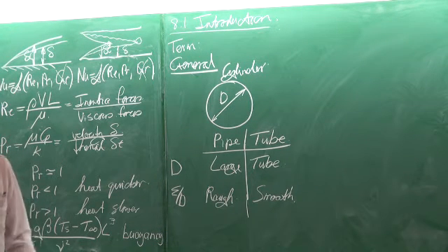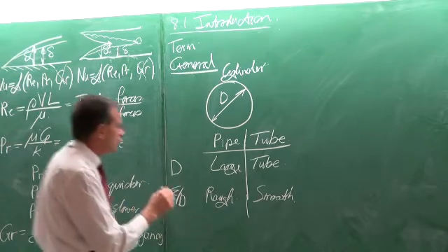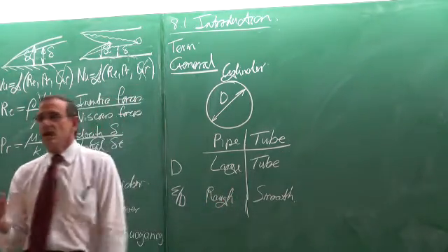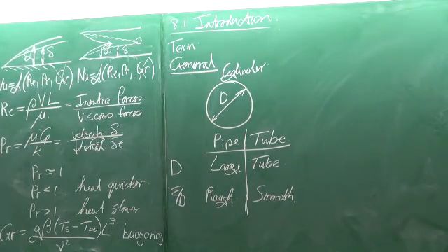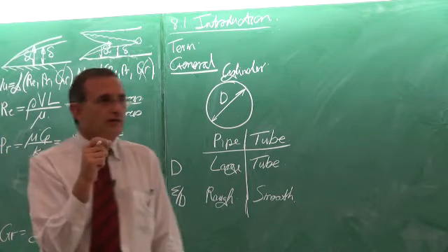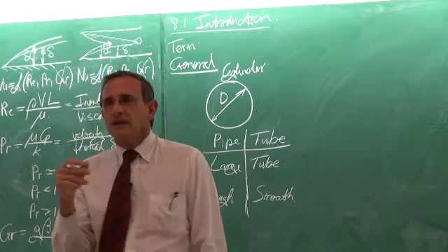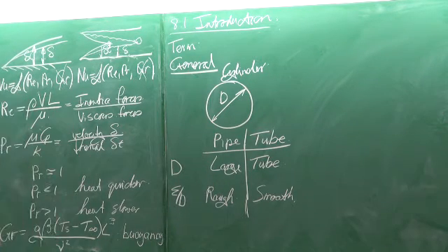However, if you're going to work in industry with pipes and tubes, these days almost all tubes or pipes, whatever you want to use, if you measure their surface roughness and divide it by the diameter, you will find that for all practical purposes they're all smooth.